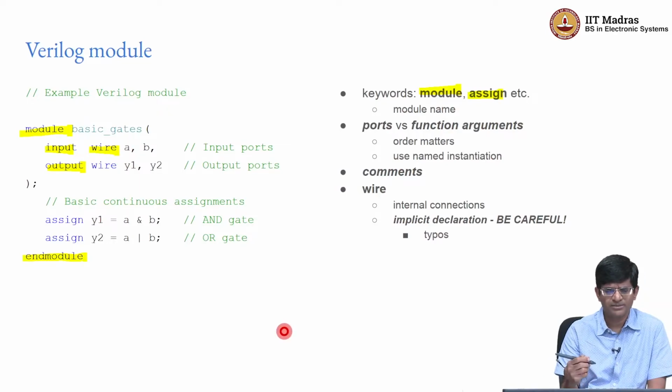The reason for that is because unlike in C, where you typically have functions with a small number of parameters and a single return value, very often in Verilog you have a very large number of ports associated with the module, multiple inputs, multiple outputs, potentially even the so-called inout kind of port, which is rare and ideally you shouldn't use unless you are very clear about why you are using it.